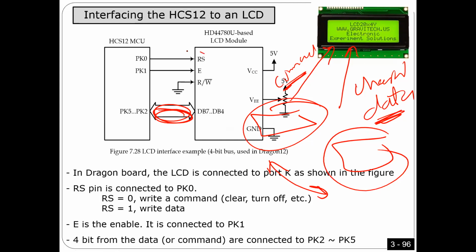That is why we have this pin here. They made this pin so that before I send a byte to the LCD, I have to tell the LCD what is coming to it: data or a command. How? This way. Look here, guys. If you put 0 here, you are telling the LCD that what I'm sending is a command, not the ASCII for a character.